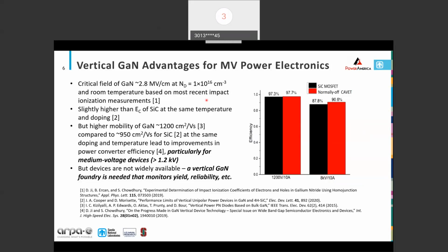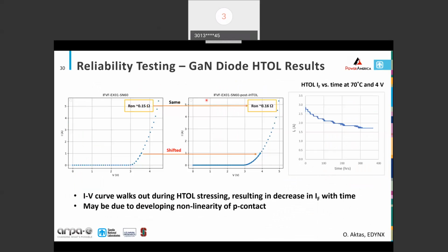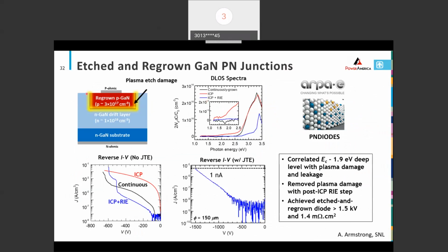Thanks. What are the technical challenges in developing GaN JBS diodes with higher voltage, say greater than 10 kV? And do you think that GaN JBS diodes have potential to become superior to SiC JBS diodes at 10 kV or higher voltage? Right. So I would say the main challenge really is, I guess I could go back to that one slide. Yeah, this, so the quality of this regrown interface. This PN junction is going to support that high voltage. So this has got to be not just high breakdown, but low leakage.